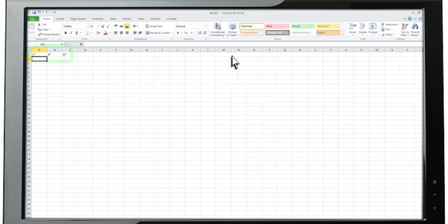Now, launch your data entry application, such as Microsoft Excel. Label the fields as you need them, then highlight the field where you want your first data to start. Start taking measurements. The data will automatically populate each of the fields just as you configured it in the DataCatcher options window.